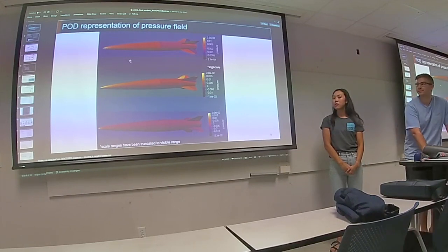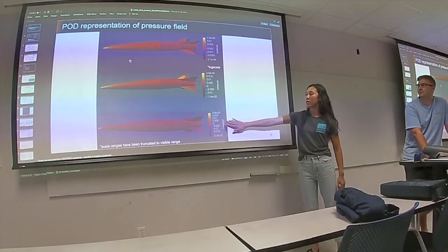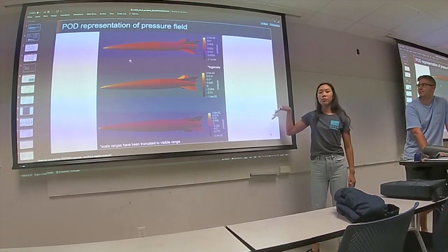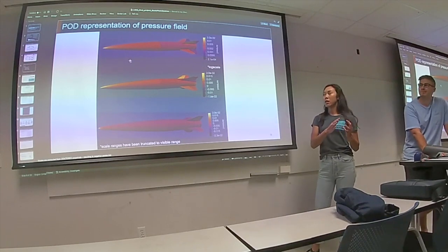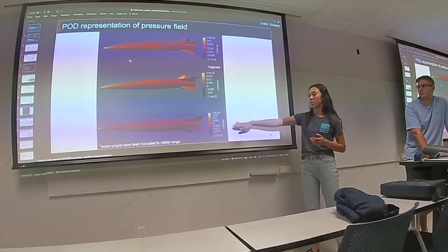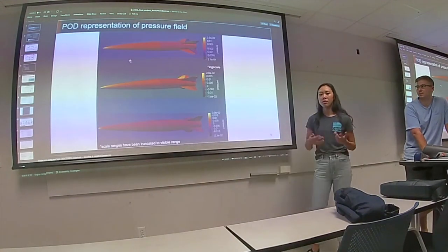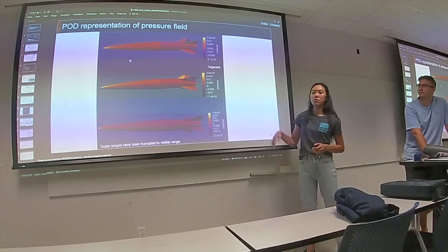So what is negative pressure? This is a little bit misleading. These are pressure modes. When we center the snapshot matrix, so that bias there, we subtract that from all of our snapshots. That creates some negative values. When we compute the SVD, these are the modes we get. So it's dimensionless, it's not really negative pressure. These are the vectors? Yes, these are the modes. Okay, I see.